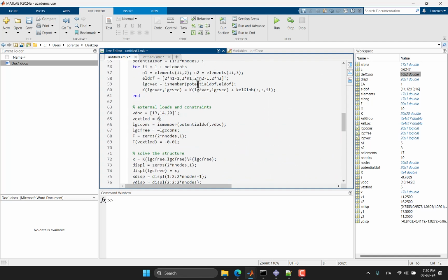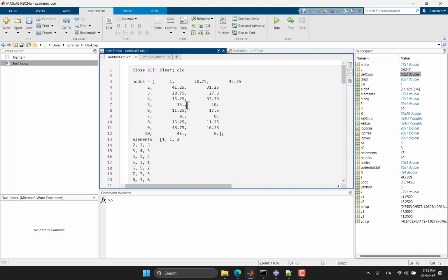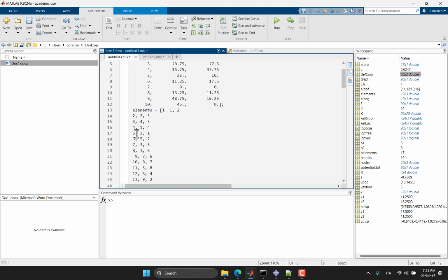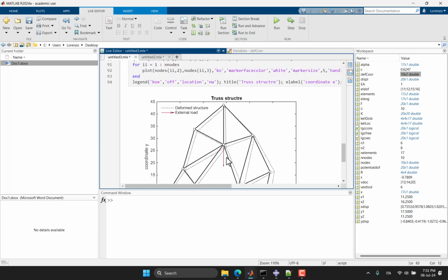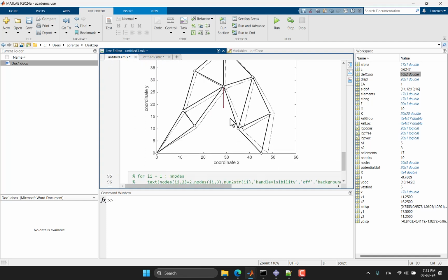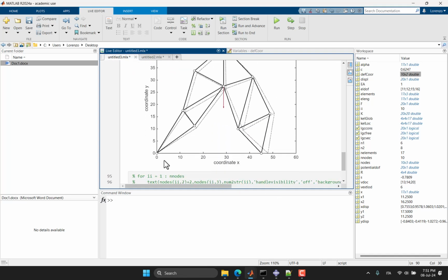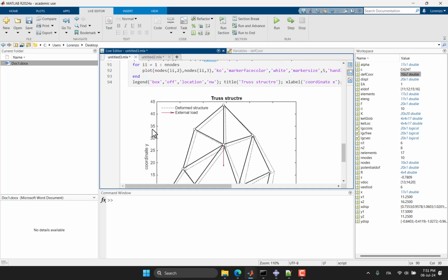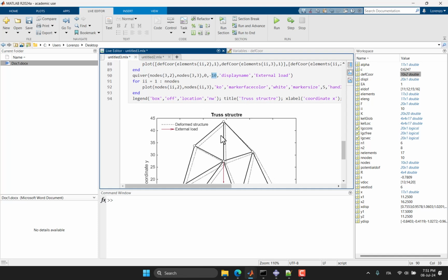And that's it. If you change the scale of the structure, that is, if the coordinates of the elements are quite different, probably also the scale of the arrows that represent the loads must be updated. Here I have used a magnitude of 10 that is good with respect to the size of this structure. If the structure that you draw will span from 0 to 2000 as x, probably you will have to update accordingly also the scaling of the arrows that represent the load.